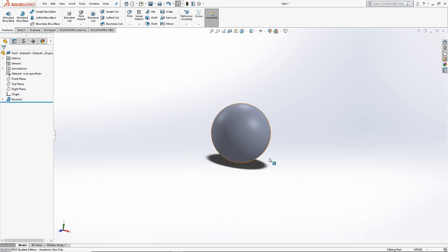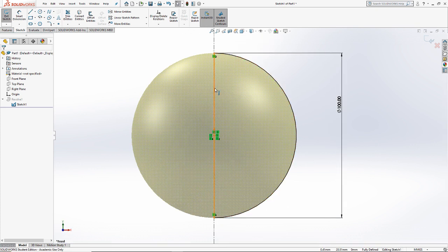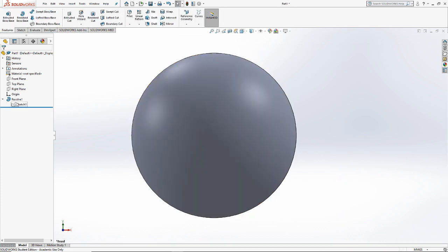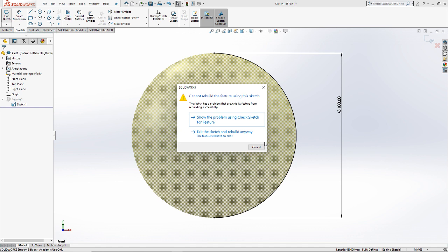So I'm guessing if you're following along, that probably went well, right? For those of you who had errors, did it say something like no enclosed region? A pretty common mistake when creating revolved extrusions is for people to forget to close half their cross-section. So looking at this semicircle, if, for example, you left this line behind and you only created half a circle, your circle isn't going to have an enclosed region to sweep. So when you attempt to create a sphere like that, you end up with a broken extrusion. Don't forget to enclose your regions.